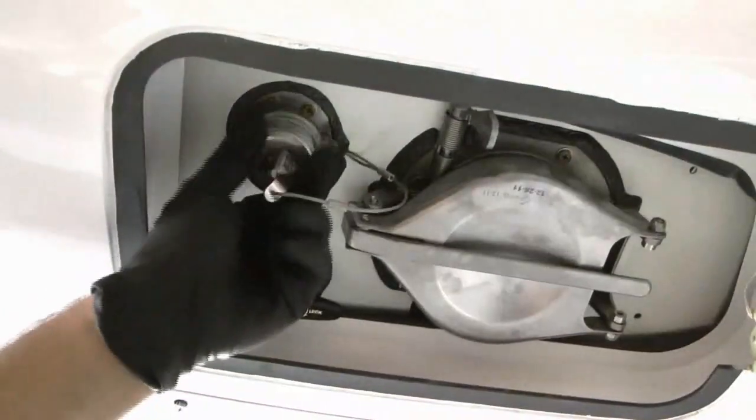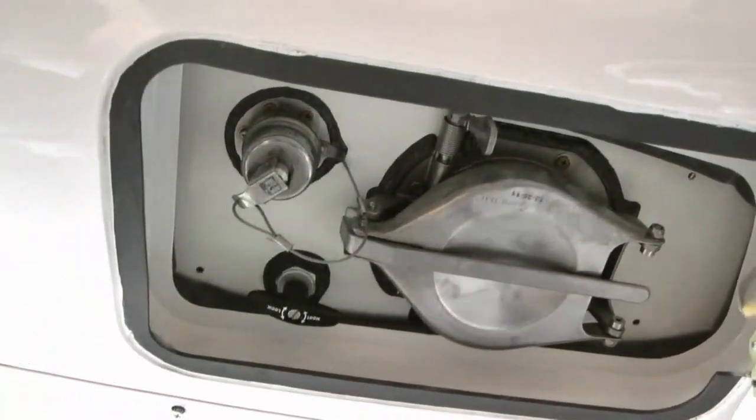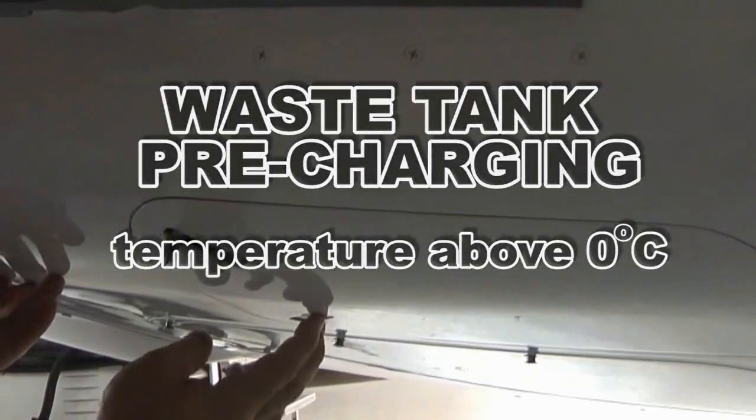Install the rinse nipple cap on the RTS rinse valve. Close the access door. It will close only if the RTS waste drain valve is correctly closed. Waste tank pre-charging.